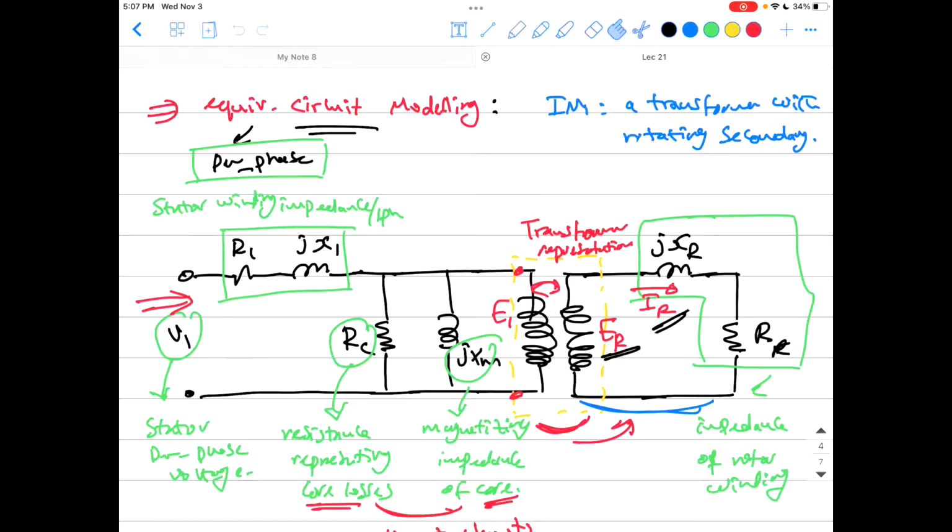The theory of operation of the induction machine depends on the electric current in the rotor coming by induction from the stator. You push electric current to the stator and this creates a magnetic field that is time varying with respect to the rotor, so the rotor has an induced voltage. Because we short-circuit the rotor winding, a current moves in those windings creating its own magnetic field. The interaction between the stator's main magnetic field and the rotor's induced magnetic field creates torque and the rotor starts rotating.